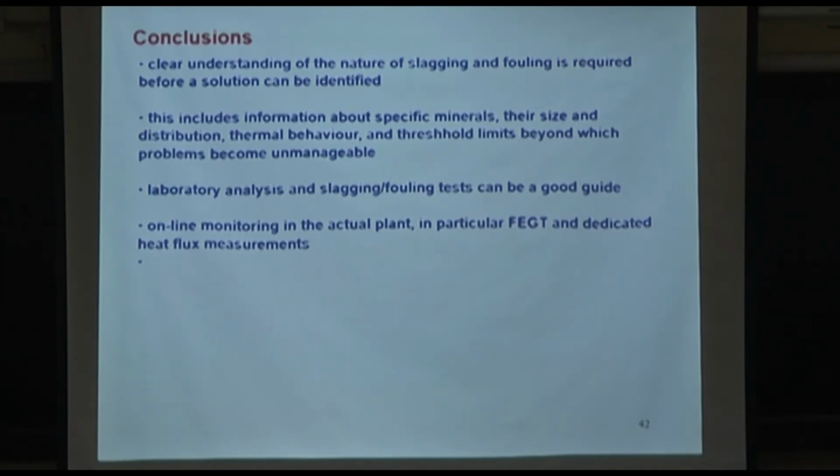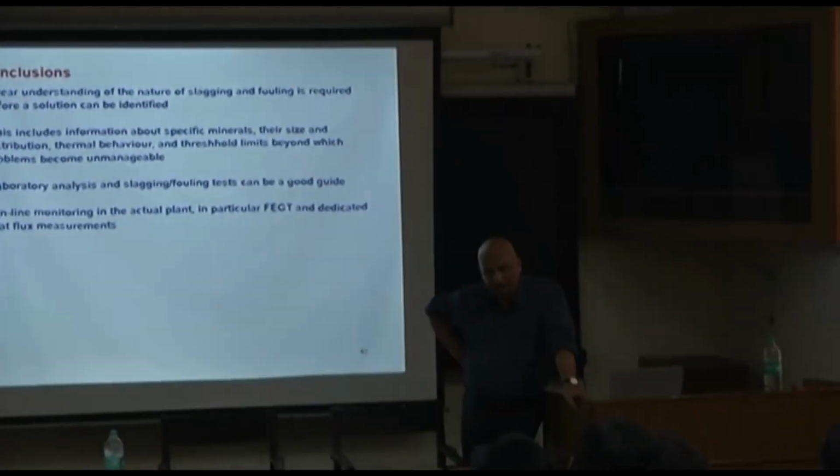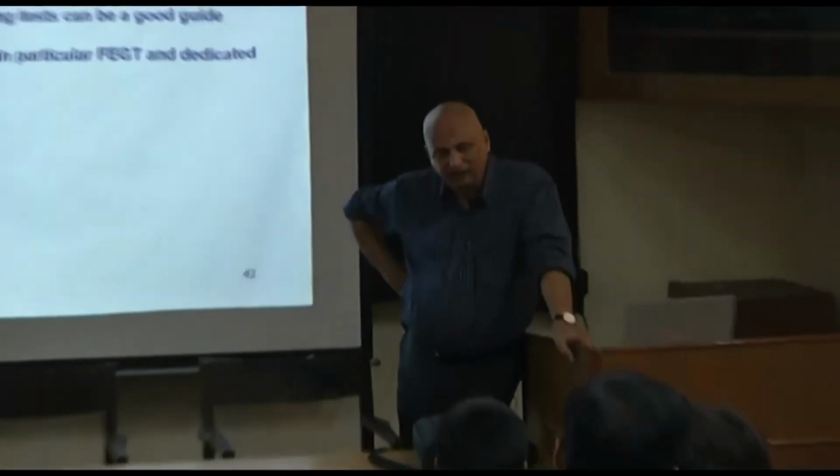Anyway, what will happen is the calcium oxide will not stay in the bed. Calcium oxide is very fine. Have you seen cement? Cement is extremely fine. So calcium oxide is very fine, and unless it is fine, it's not going to react with sulfur dioxide. It will take a very long time to react with sulfur dioxide to form calcium sulfate. But because of its size, it goes away from the bed.